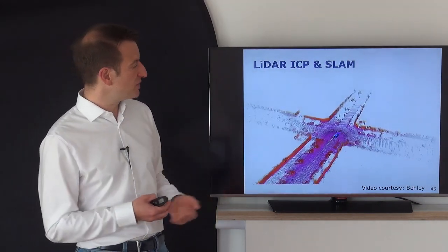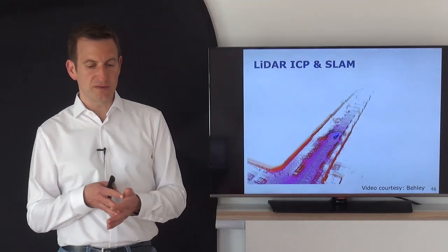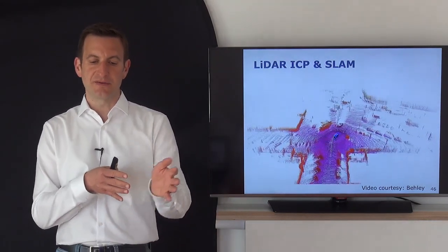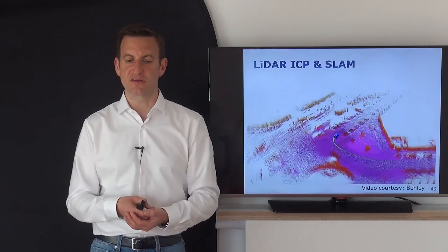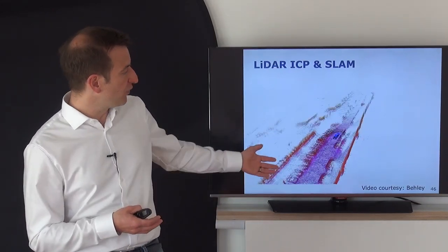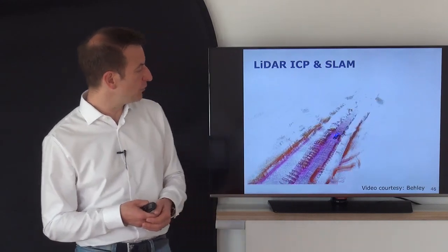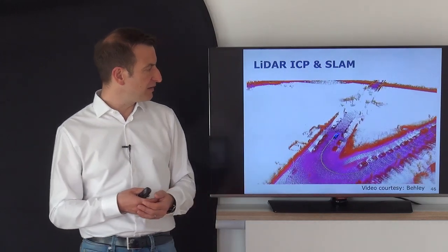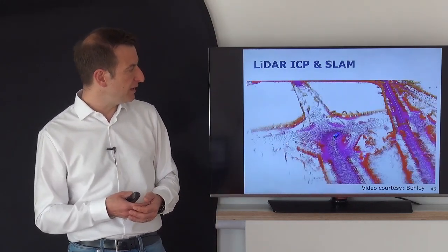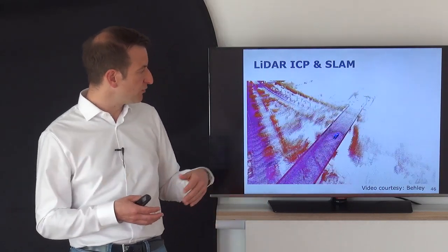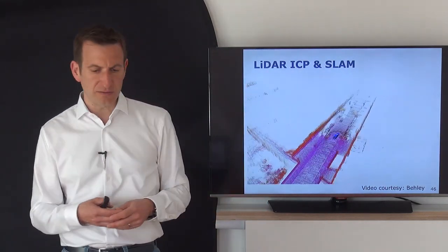This approach registers the 3D point clouds that are coming in against each other and builds a graph-like structure which is then used in a SLAM algorithm to estimate where the vehicle is going. So far we are still driving open loop. There has been no loop closure or similar information, so all the pose corrections here are done using the ICP algorithm. You can see the car drives over a bridge over that road. It will drive around. This is all basically ICP registrations.